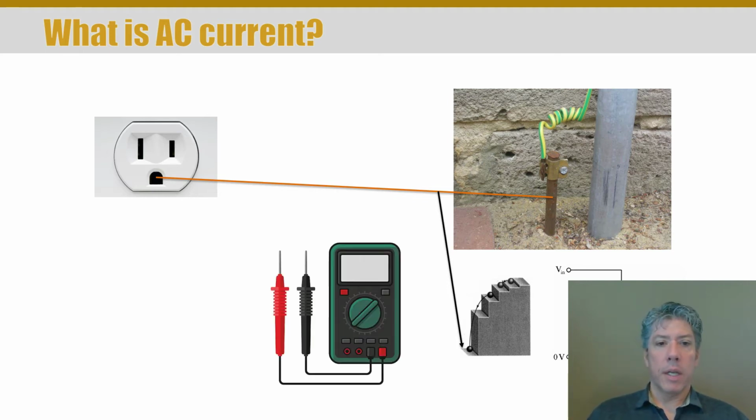Okay. Now let's take a multimeter and let's start measuring a few things. We'll put the black lead on ground. Okay, that is our 0 volt reference. So we'll put it there. And what if we put the red lead on ground? What reading would we get? We get 0. We're measuring a height from reference to reference. I mean, how high is the ground off of itself? 0 feet, right? You don't need a measuring tape to figure that out.